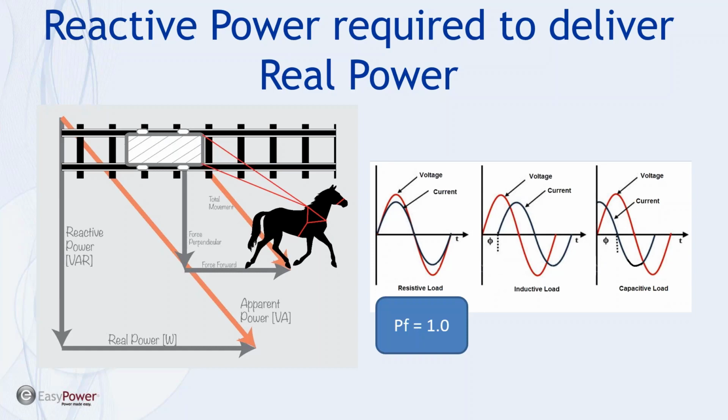Well, in more technical terms, when the voltage and current are both in the same phase, as they would be in a resistive load, the power factor is considered to be 1. But as soon as the voltage or current has to change phases because of this response to the reactive demand of the loads, we have a change in power factor.